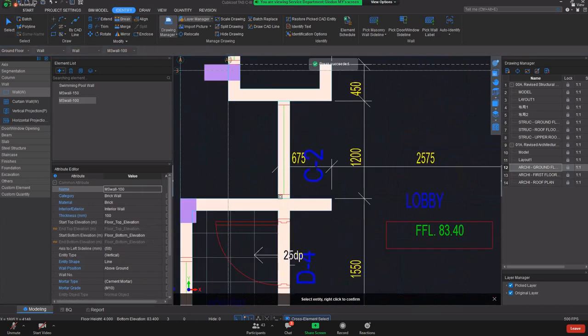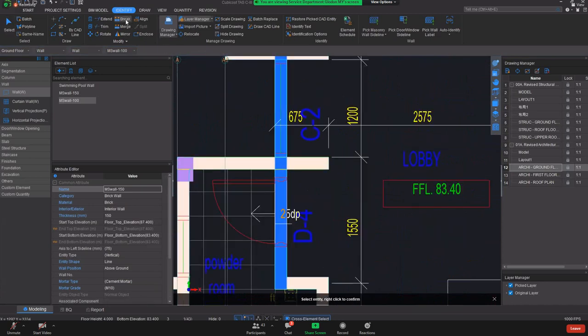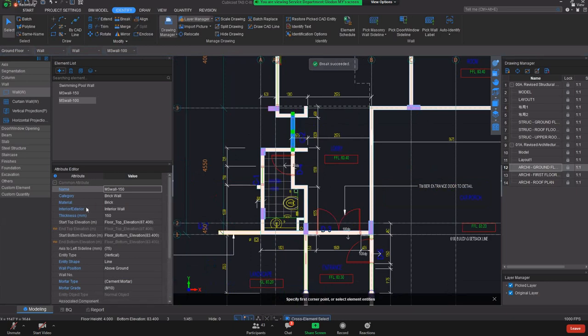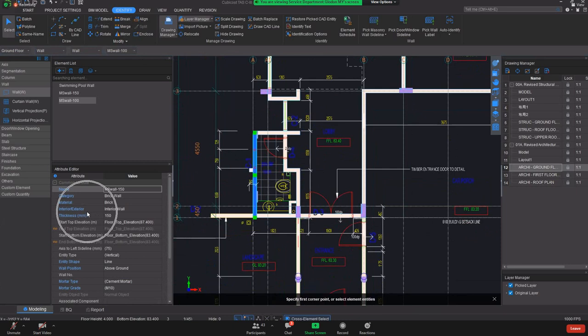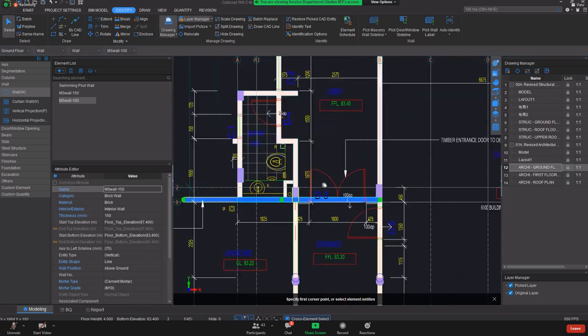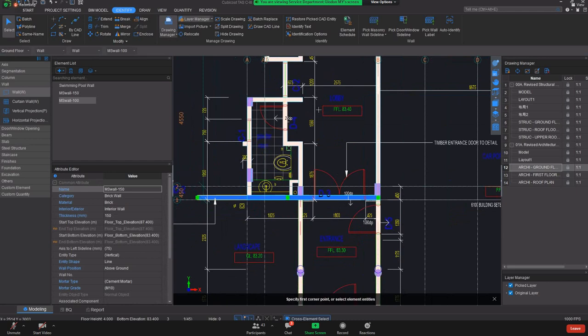And also, for example, this one, and then break it into half. And this as well. Try to break them into half, because later we are going to change the category of the wall to become external wall. This one also needs to change. I'll give you 5 minutes to change it.